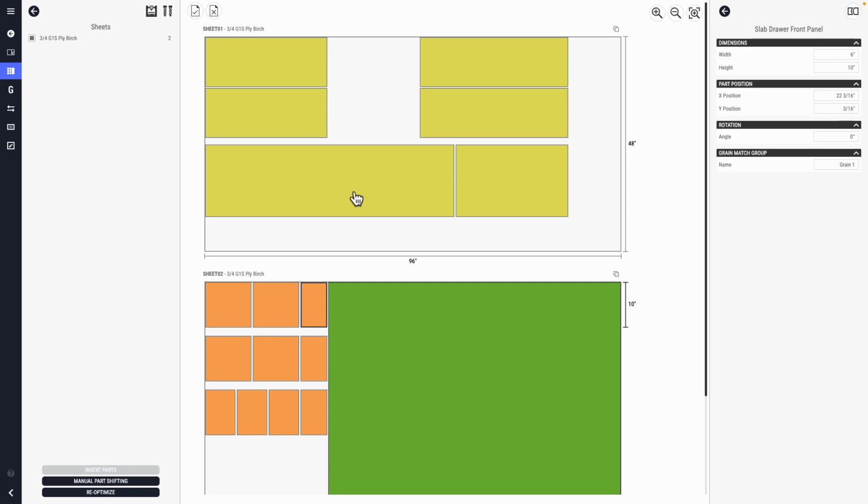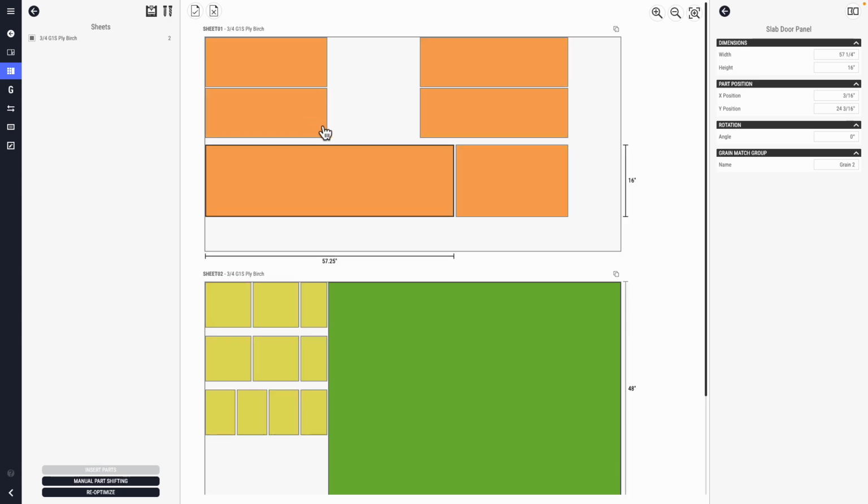For instance, if I was using some full overlay assignment, where I'm keeping 1/8 inch reveal between all the fronts, but all I have to work with is a 3/8 inch compression bit, then CAD Builder will still nest those, will attempt to match them as best as it can, but obviously we'll have to make the spacing 3/8 as opposed to the standard 1/8 of an inch. Although in this case, we have enough space between them that doesn't happen.